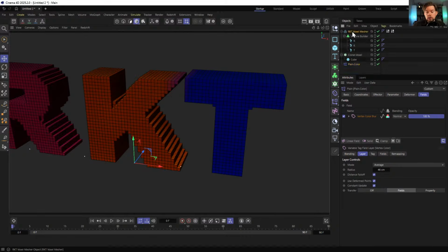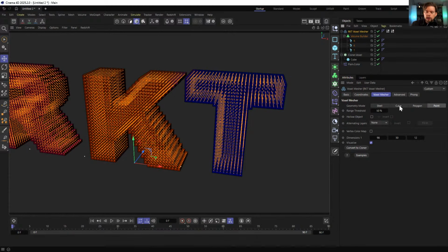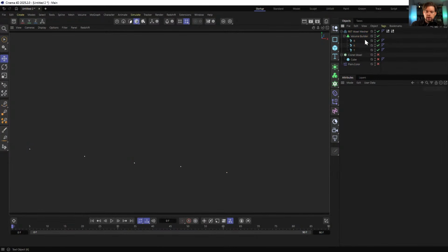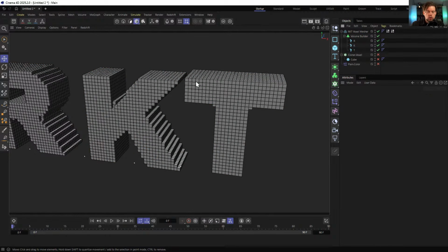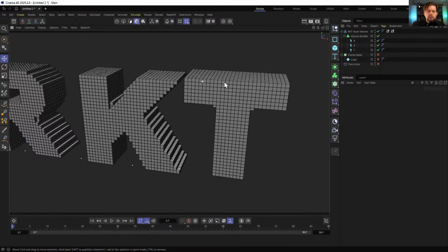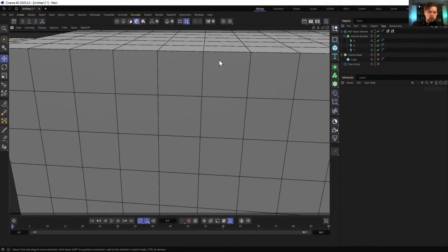And the reason I did it into the cloner system is, let me turn off a bunch of that stuff. So now we're back to just the voxel mesher. If I was in cube mode, then we get all of these cubes, but these cubes are just geometry floating in space. And even though we can't really see it right now, this is a full cube, that's a full cube. So there's technically two polygons intersecting each other right there. And if the vertex map was trying to colorize this, it would colorize just this point here, and it would essentially blur. So every cube would be crossfading between 4, or I guess technically 8 different colors of all of its points. So by doing it per clone, we're making it so that they're solid colored.